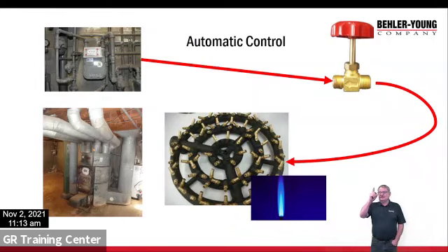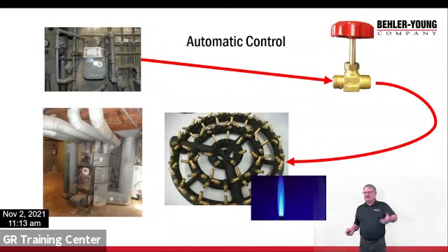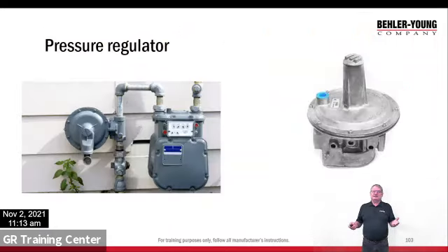Anyways, so if I just had a gas valve and a pilot, right? We got a pilot light sitting there. We light the pilot and the gas, and I open the gas valve and the furnace comes on. Great. What happens if that pilot goes out and the gas valve opens? I'm going to build up gas, get above its explosive limit, and boom. All right, so in this scenario, I have no safety at all.